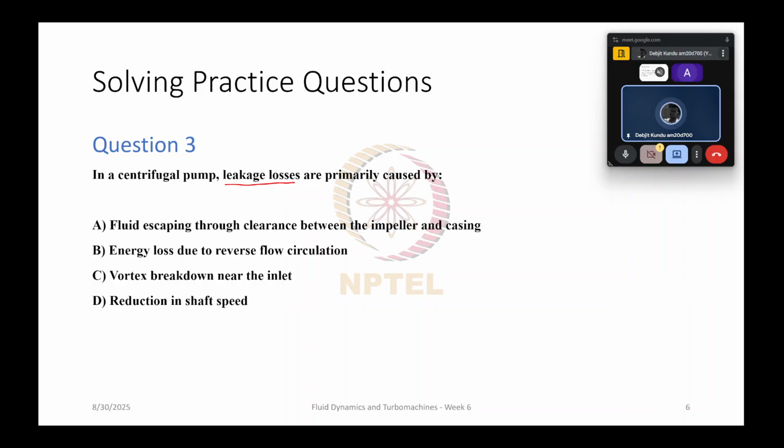For that, you apply the isentropic expansion or contraction formula, and then relate that to enthalpy, and those differences would give you the answer. So there are a few particular topics from which numericals can come, and if you just understand the basic principles of them, then you're good to go.